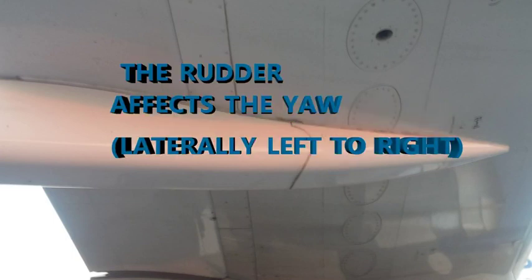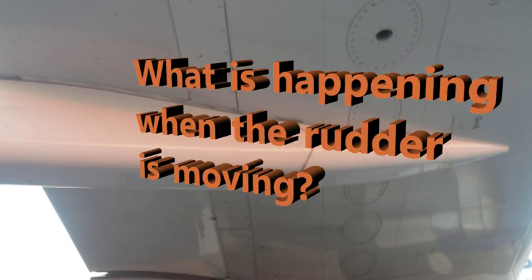Number three is going to be your rudder. The rudder is affecting the yaw. Okay, and that's kind of like the pulling laterally from right to left. So that's different from the rolling, which dips downward to the right or left. The yaw is keeping the same axis, moving right to left. And this is controlling adverse yaw, so keeping the plane more centered. It's also not the primary control used to turn the plane, but again, it's just helping with the yaw, so there's not an imbalance there.